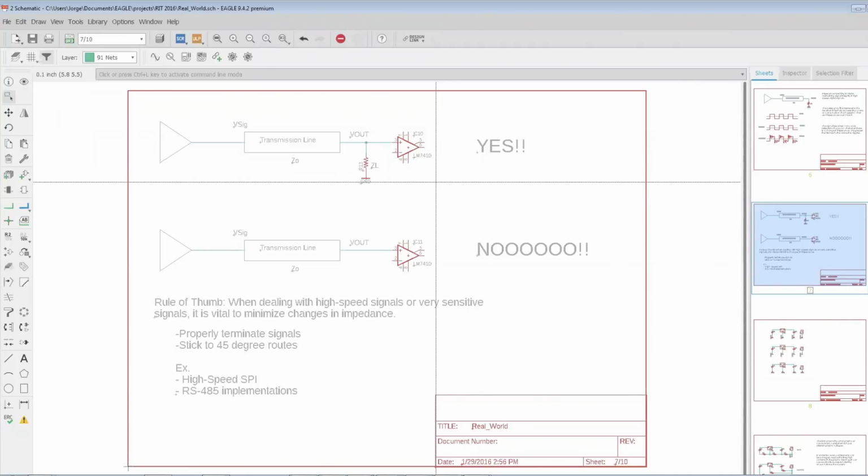You need very expensive equipment to see this physically, but when you start analyzing, we all know this fundamentally, but because of daily practice and working, sometimes we lose sight of this fact. Electric current always flows in a loop. For every signal, you have the current going through the signal path and then coming back through a return path. Every signal on your board does this. It goes out and the current flows back. For most of us, we just let it flow to ground.